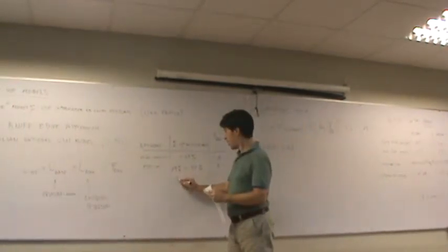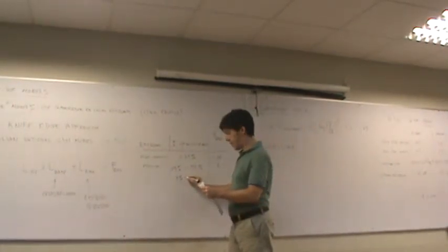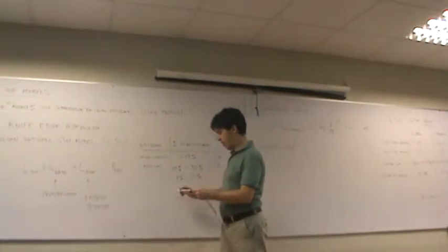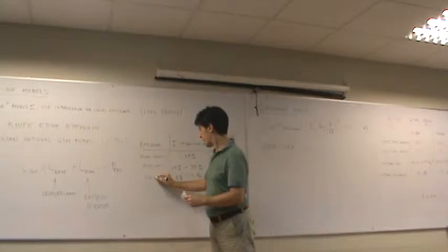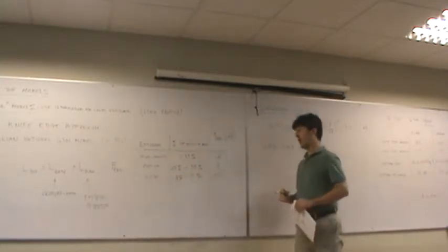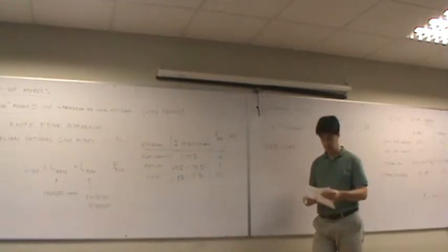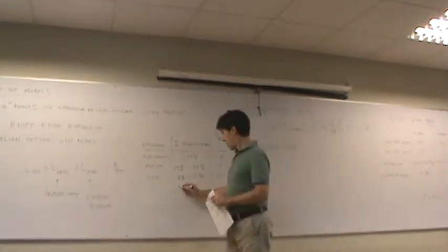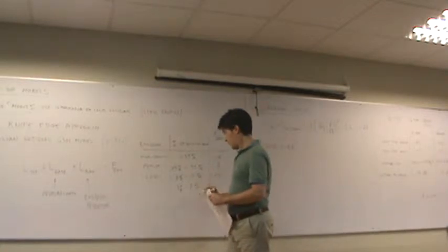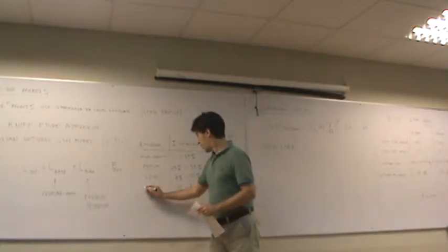If the percentage of built area is between 8 and 15, this is low density, and we reduce the losses by 10 dB. Then 3% to 8%, we call that suburban.